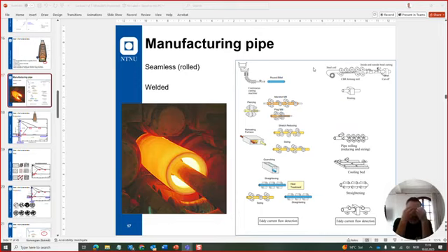But what is special about line pipe is that very often it is spooled onto a huge drum. Then this drum is hoisted on board a boat or wherever you are laying your pipe. If it is in the desert, it will be on a huge truck. Whenever the drum is getting empty, you stop and weld it together with the pipe on the next drum, and you continue laying your pipe. Line pipe.